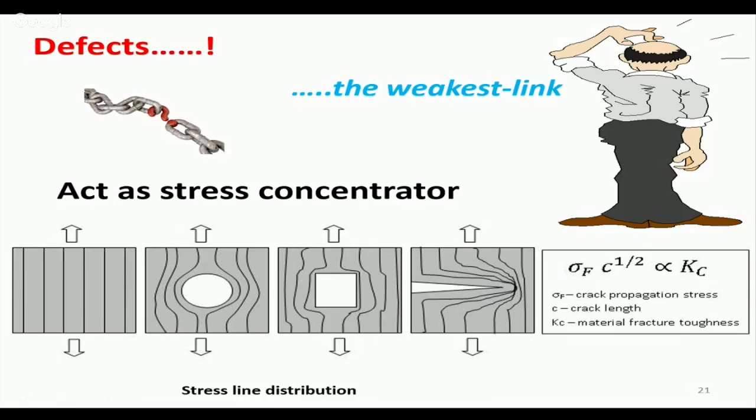So that is why even if you have cracks in the metal, even if you have cracks in the plastics, we still use them. But for ceramics, glass or crockery, as you see the notch, we just say you have to throw it away, otherwise you will encounter an accident, right? So ceramics have low fracture toughness, and in metals there will be plastic deformation and there will be some toughening mechanism. But in case of ceramics, what we have to do is play with the microstructure to make it tough.